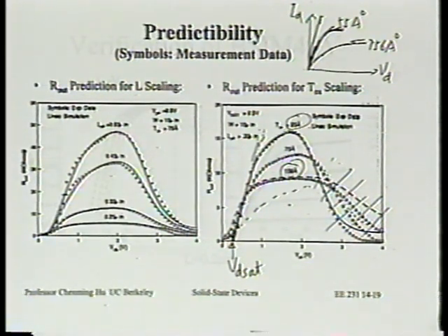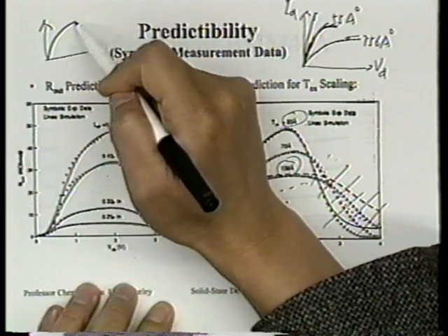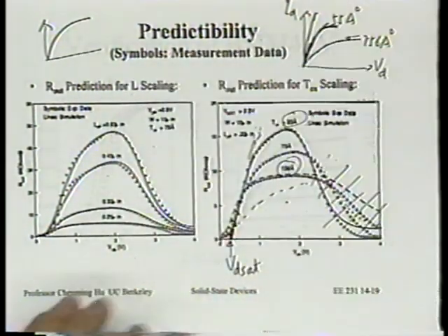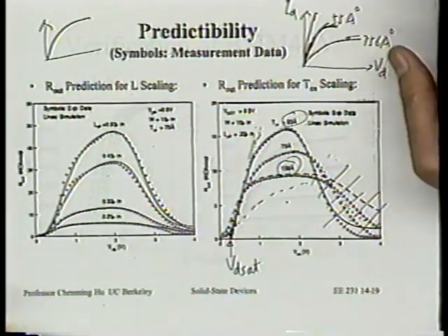Do you know what I mean? Because experimentally, there's no way to define VD set. You get an IV curve, where do you point and call it VD set? You see what I mean? You measure the IV curve, ID versus VD. You can measure as many such curves as you want. How do you define VD set? Yes? So experimentally, it's very difficult to determine VD set.